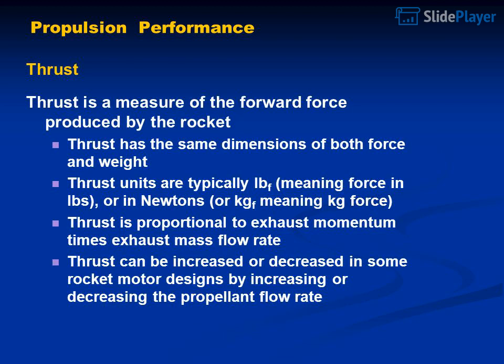Propulsion performance. Thrust. Thrust is a measure of the forward force produced by the rocket. Thrust has the same dimensions of both force and weight. Thrust units are typically lbf, meaning force in pounds, or newtons, or kgf, meaning kg force. Thrust is proportional to exhaust momentum times exhaust mass flow rate. Thrust can be increased or decreased in some rocket motor designs by increasing or decreasing the propellant flow rate.